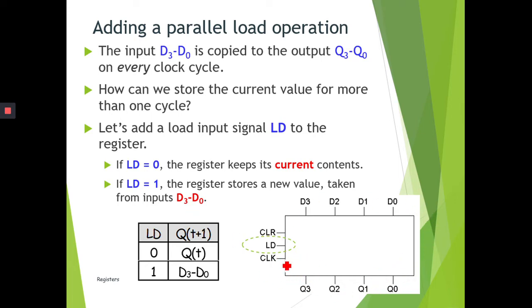And this is how the diagram looks. Try to familiarize yourself with the diagram, because later when we work on the lab, you are going to see these kinds of symbols. When you look at the symbols, you can then process them. They have 4 inputs, D0 to D3, and they have clear, load, and clock inputs, and also 4 outputs. This must be a 4-bit flip-flop register.